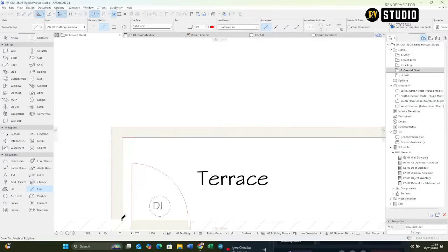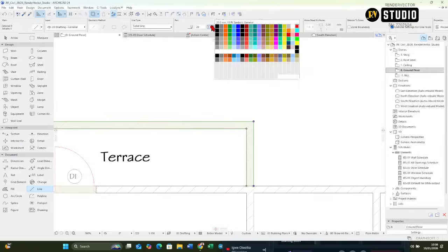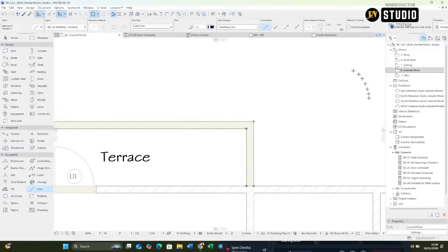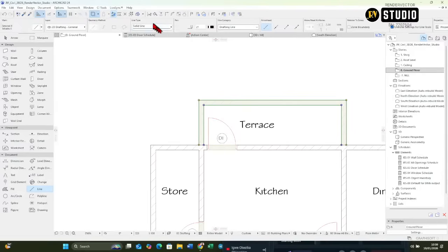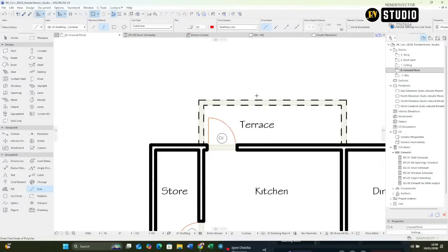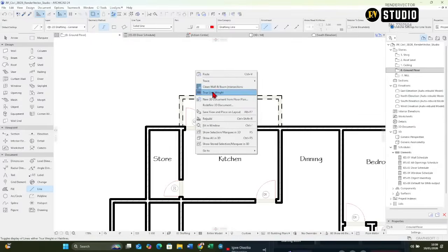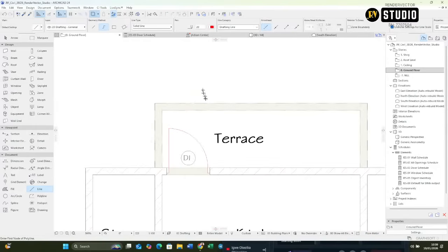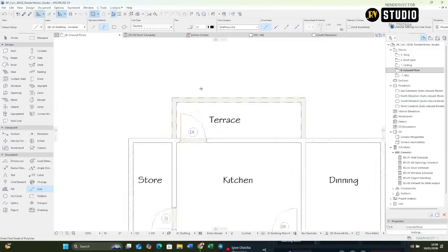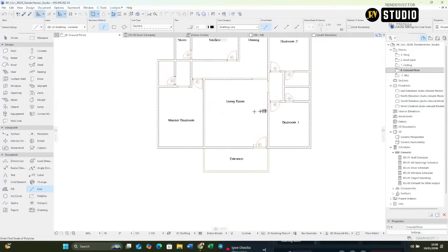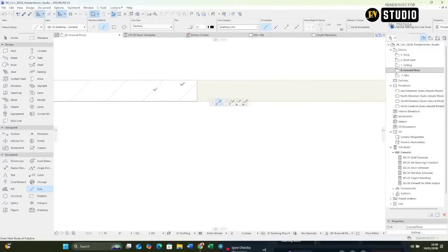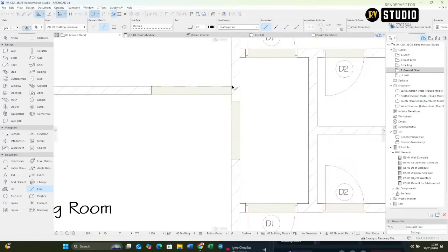When you trace out this wall, highlight the line you selected. Make sure it's black, a little bit thick, not as thick as the wall thickness. Then you now set it to dotted lines. So when you set it to dotted lines, you check your true line width and see if it's okay. Okay, it's nice now. So you go back to your settings and then you hold your alternate and copy. Left click. Do the same to places where these things pass through. You have to trace them out like that.